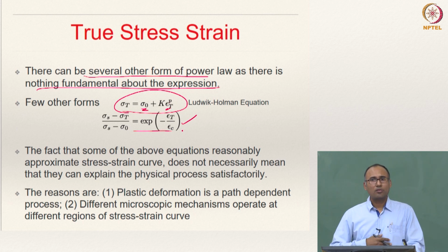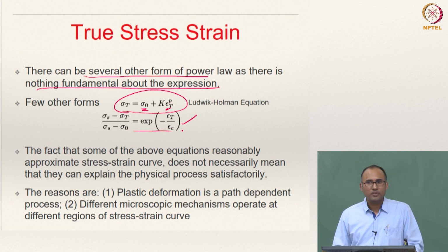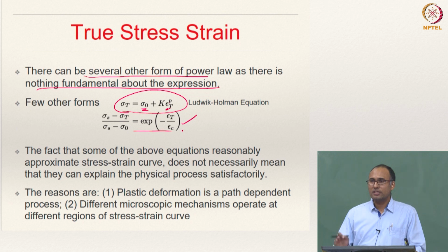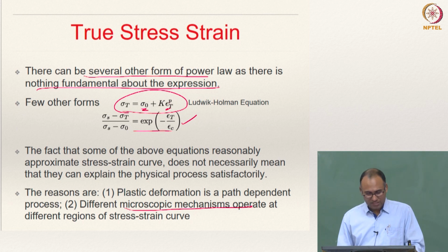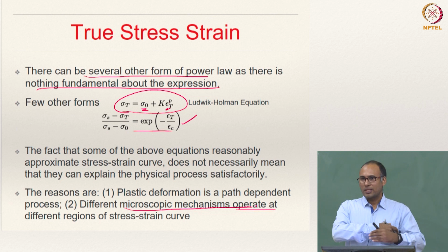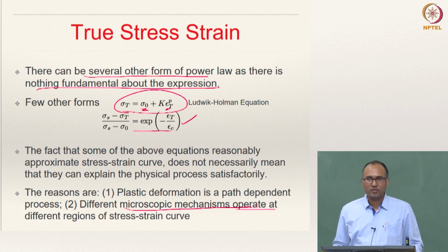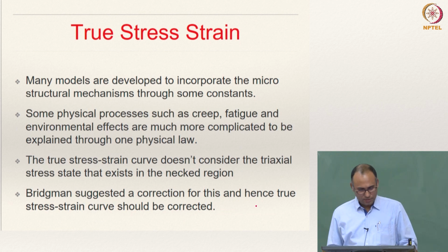If you are modeling plastic deformation in a material, it is extremely important that you carefully follow the path dependency. Otherwise, you will be estimating your stress state in a completely wrong manner than what it is supposed to be. And of course, we have discussed that there are different microscopic mechanisms that can be operating at different regions of the stress strain curve. So you possibly cannot use one law to describe every part of the stress strain curve. All right.